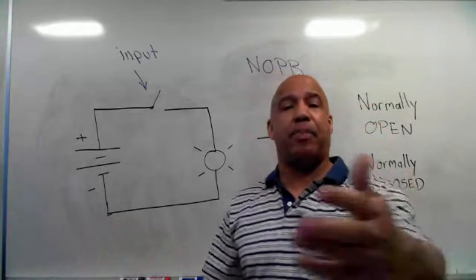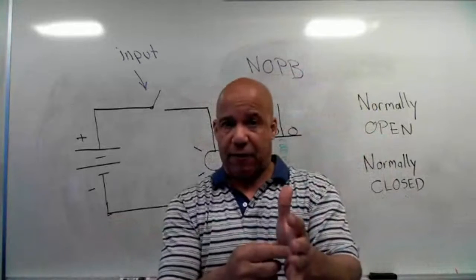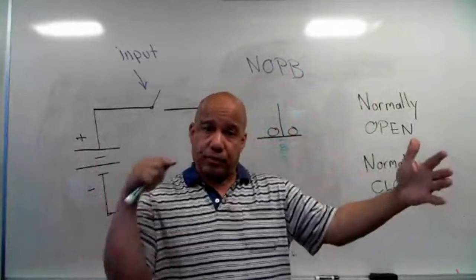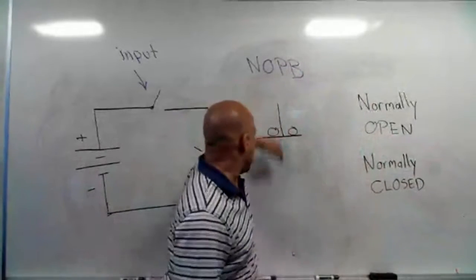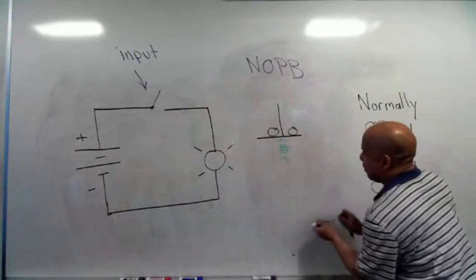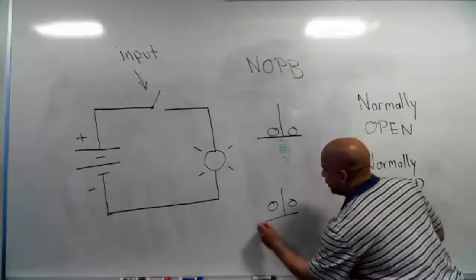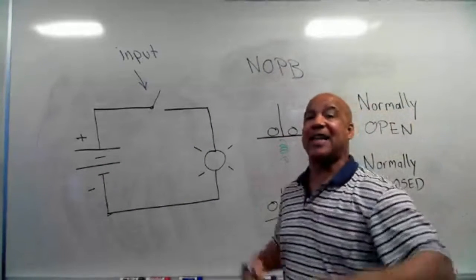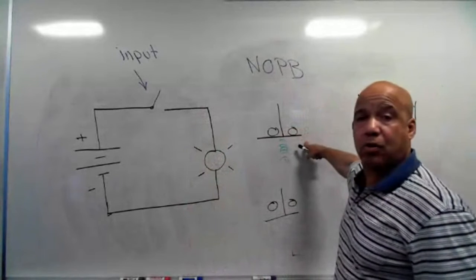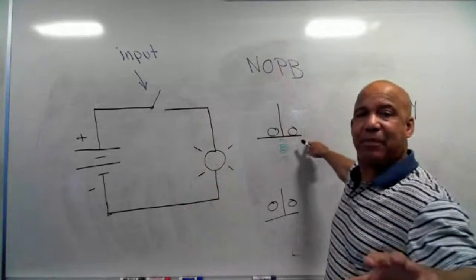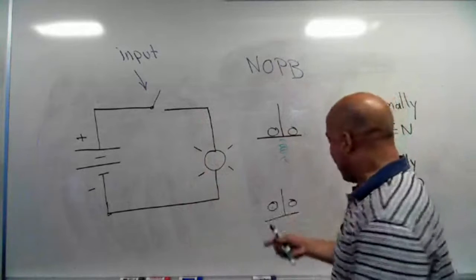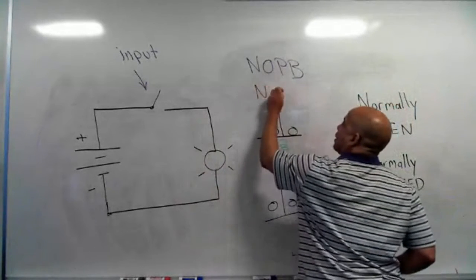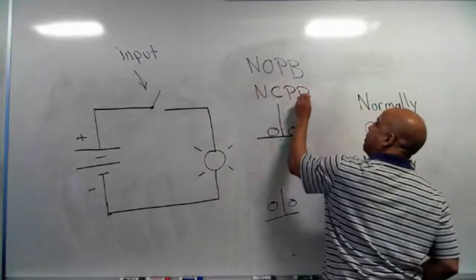It would be like the button on your car door that turns your inside light off and on, or the one on your refrigerator. If you open the door, and you press that button with your finger, you actually turn the light off. But when that button is just sitting on the table, and you're not interacting with it at all, in its normal state, that switch is closed. So the way you would name this button, in this case, would be a normally closed push button.